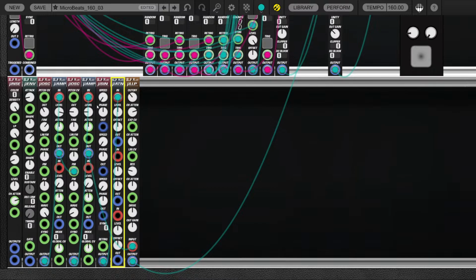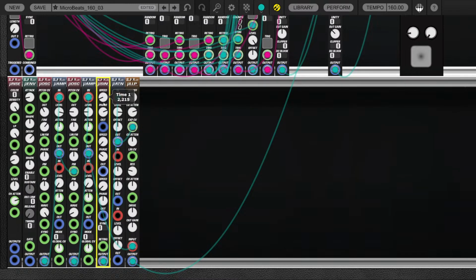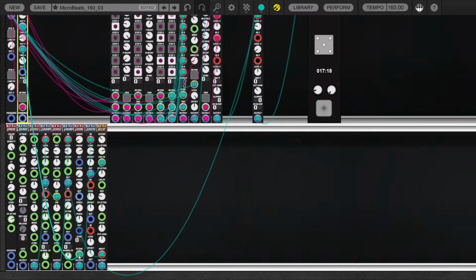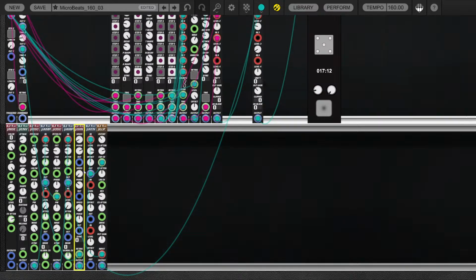We'll use the combined output of the sine LFO, which is a combination of all three LFOs. We will unsync it so these are free running. Now let's get some random frequencies, maybe even put them out of phase. Okay, that's great. We will patch a slow clock into the sine LFO to reset it so we can get a pattern going.